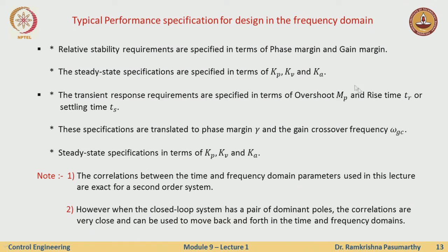Similar to the time domain, again we recollect this in terms of overshoot, the rise time or the settling time. These are now translated via appropriate formulas or relations to specifications on the gain margin and the gain crossover frequency, and steady state specifications remain the same, right.